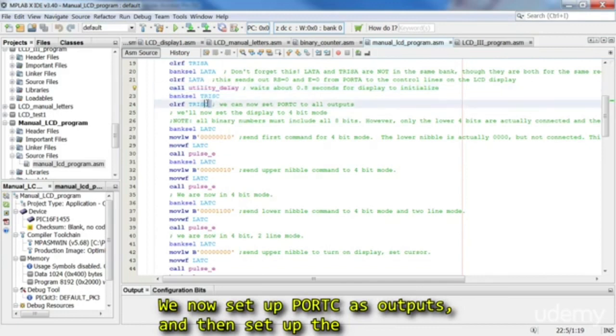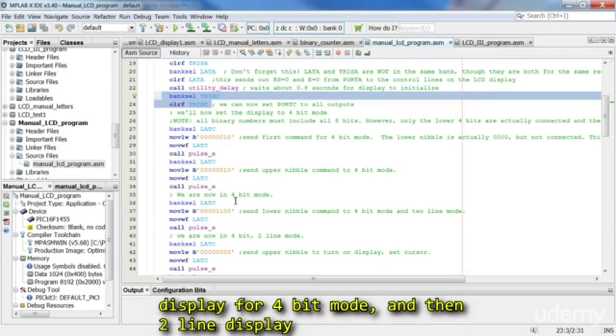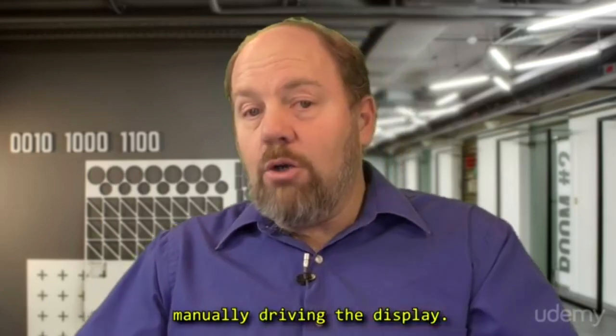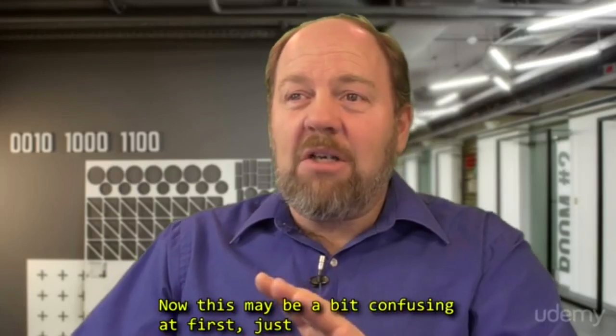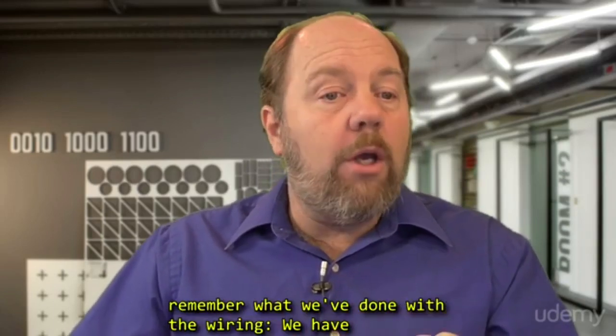We now set up port C as outputs, and then we set up the display for 4-bit mode and then 2-line display mode. Now this was done exactly the same way you did manually driving the display. Now this may be a bit confusing at first. Just remember what we've done with the wiring.